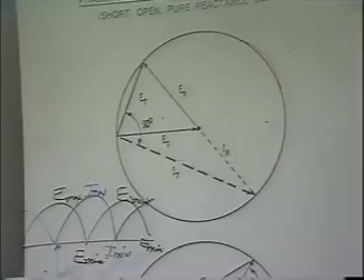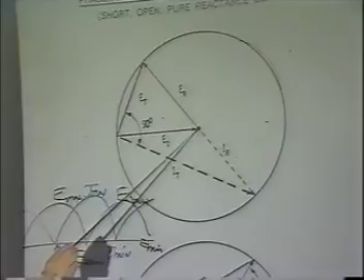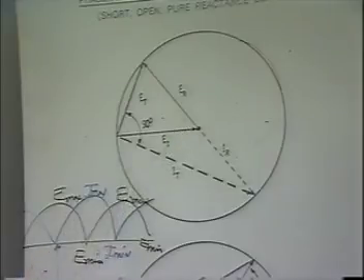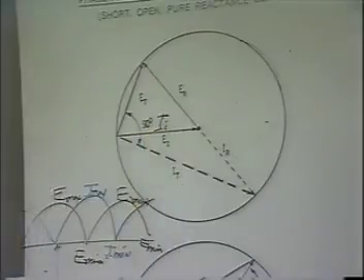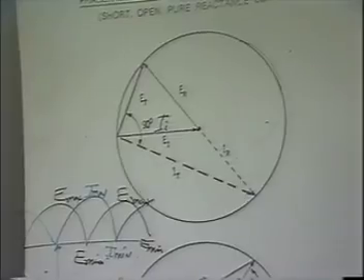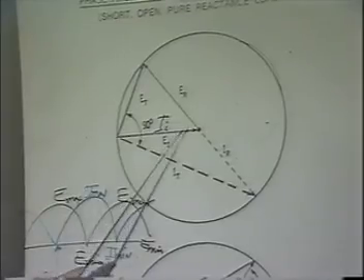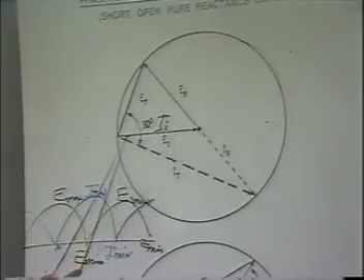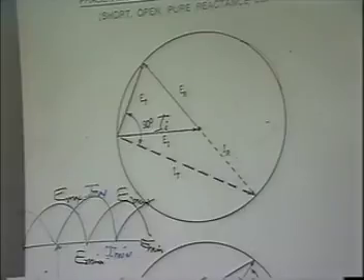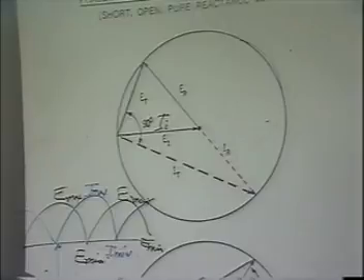Now what happened when E sub R was not here? We only ended up with Z here, right? And we said before that there is also a current here, I sub I. The two are in phase, right? If the two are in phase, now what's the phase of total voltage to total current? They're both in phase, right? No phase difference. But you see it can go anywhere from 0 then, where you have only these two signals, to where you have the two signals maximum, plus or minus 90 degrees. So the only phase difference, a maximum phase difference you can ever have is plus or minus 90 degrees.